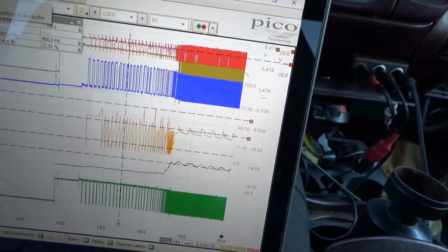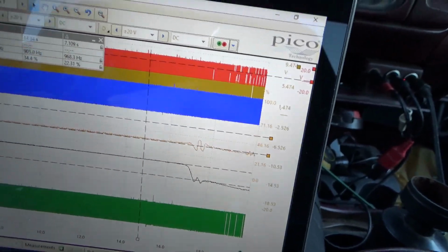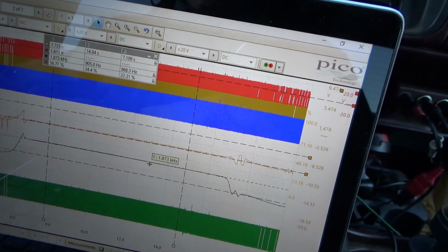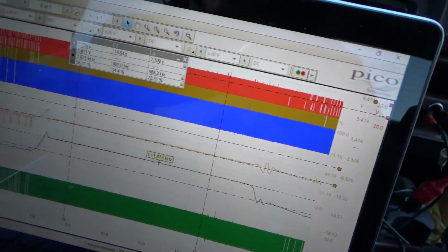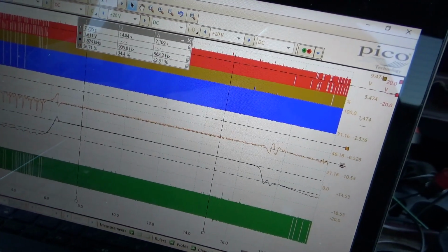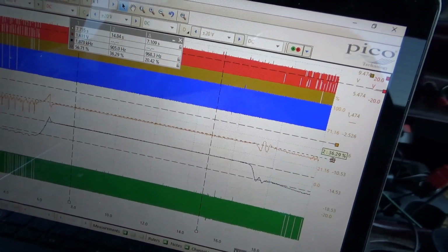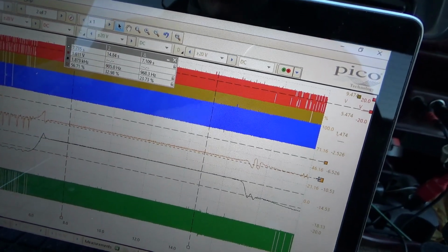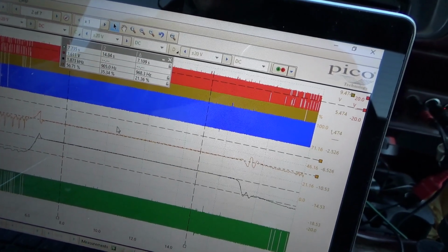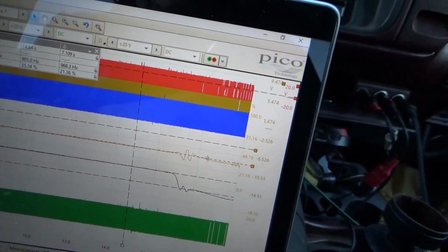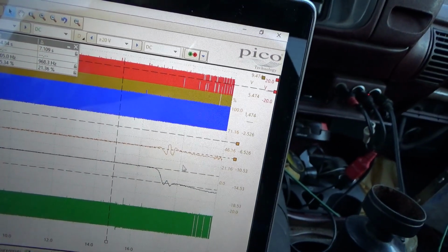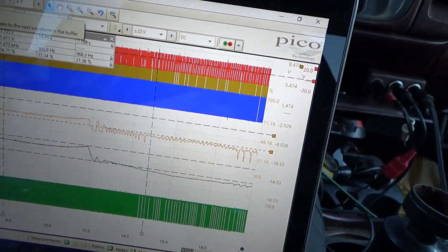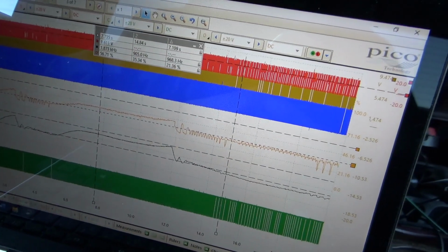Next page, give it a little throttle blip in park, and we're super smooth at about 1,800, 1,900 RPM. And the duty cycle is exactly at 33%, maybe 35%. Okay, nice and stable. Let me put it in gear right here. What happens? Duty cycle drops a little bit, even though we have more load, and it gets a little more lumpy.